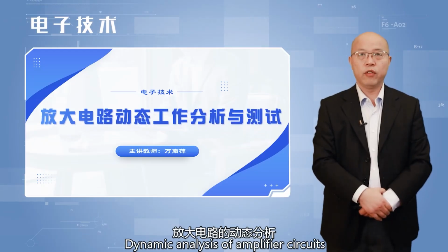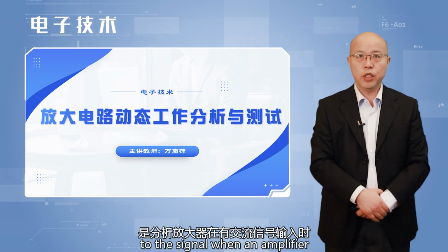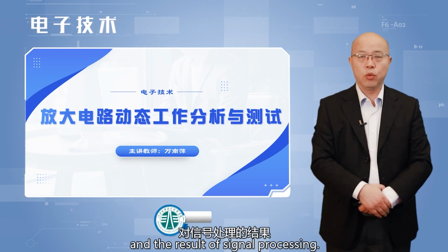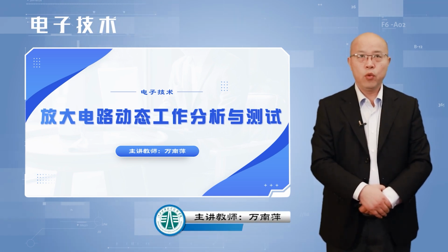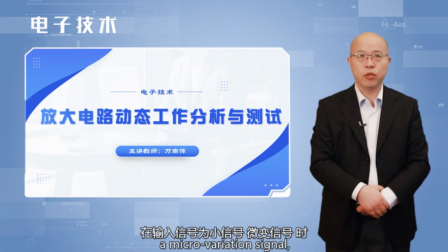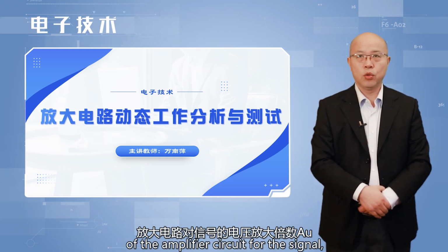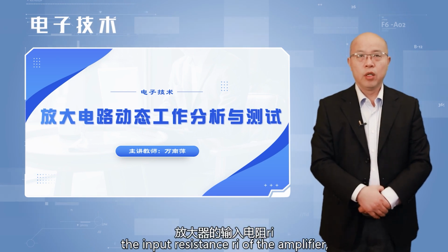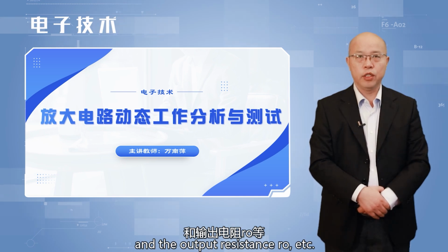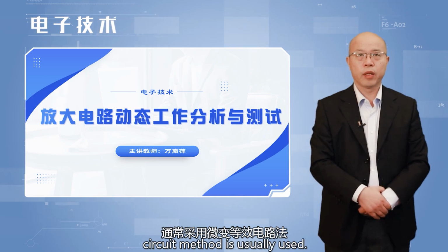The dynamic analysis of amplifier circuits is to analyze what happens to the signal when an amplifier has an alternating current signal input and the result of signal processing. We mainly discuss when the input signal is a small signal, a microvariation signal, the voltage amplification factor Au of the amplifier circuit for the signal, the input resistance Ri of the amplifier, and the output resistance Ro, etc. The small signal equivalent circuit method is usually used.